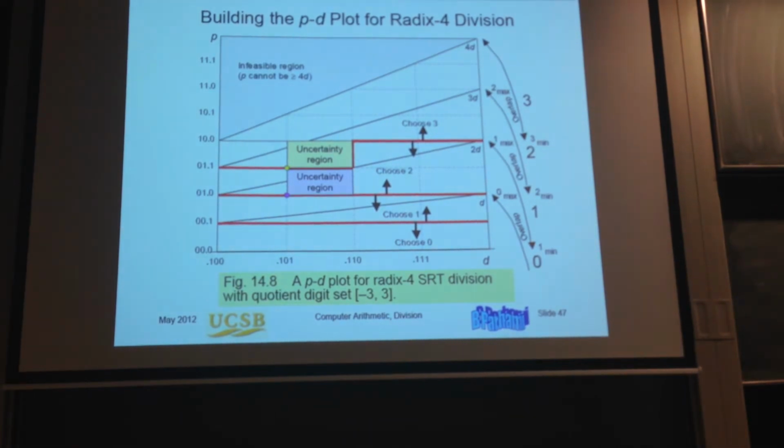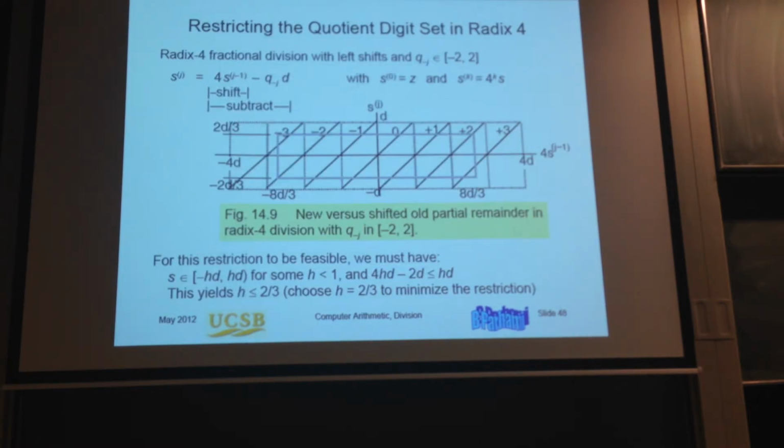Okay, now, this is assuming radix 4, SRT with digit set in -3, 3. Now, I can also try to do something else to avoid the 3A factor. Remember, we didn't like it in multiplication also. A to A, 0 are nice. But the 3A factor I have to pre-compute or to rely on some kind of carry save tree to generate it.